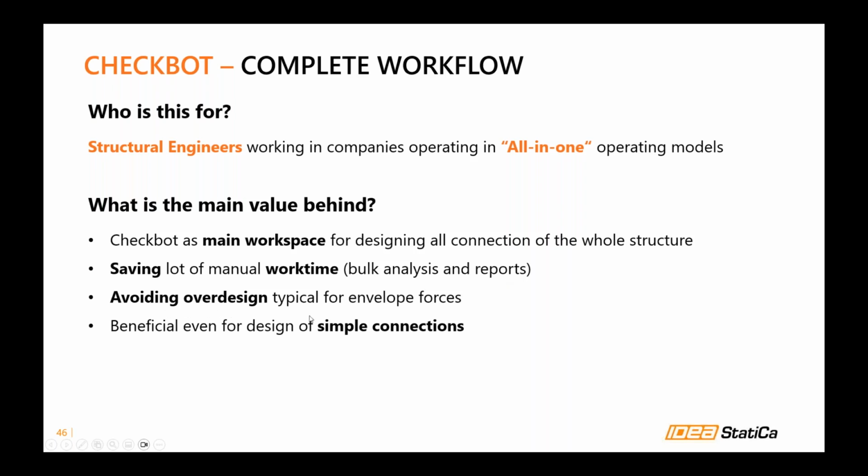Then you can avoid over design, because normally what we do is we select a typical connection, then we need to pick the envelope forces of those typical connections. Then we use the envelope forces to design the connection once, which will not be so economical. But with Checkbot, you can actually run the actual forces instead of the envelope forces.